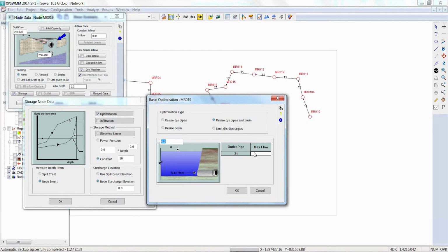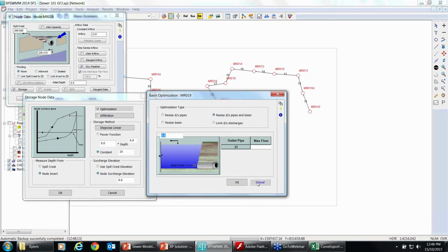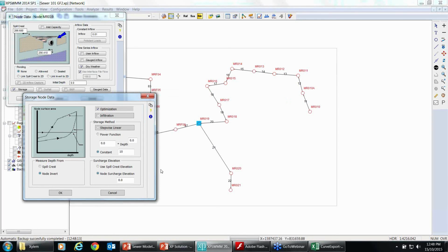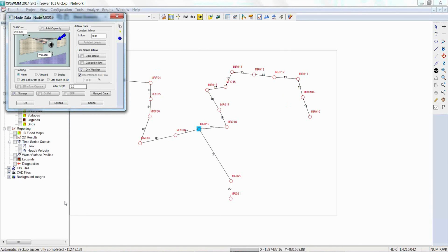And so this is a very useful arrangement, and we can nominate this maximum depth here to correlate to a freeboard at that particular location in the network. So these options are very, very simple to apply in our software. We can nominate levels at 250, which is about where this model sits. If we allowed the software to run with that optimization, it would run through a number of calculations. Probably the highest number I've forced this particular model to run through is about 75 iterations to come up with viable storages and relationships.